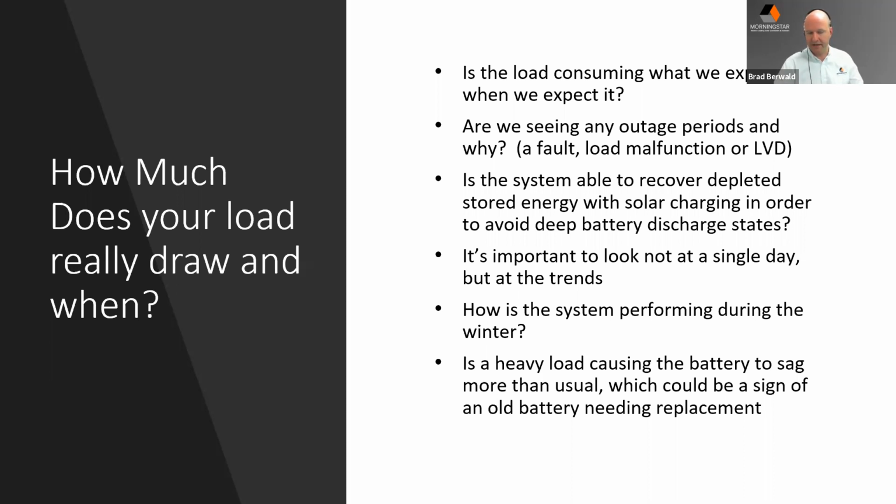And then lastly is your battery capacity adequately sized for a load. There are certain loads, pumps, large inverters, things that have a deep current draw. And when a battery begins to age, you'll find that those heavy current draws cause a significant amount of sag on a lead acid battery. One of the benefits of transitioning to lithium is they can really provide a lot of current as a strong punch. So loads that typically were a lot heavier and harder on batteries, lithium is much more capable of handling that current. You just want to make sure you're using an off-grid rated lithium battery. But checking for those heavy loads is extremely important.